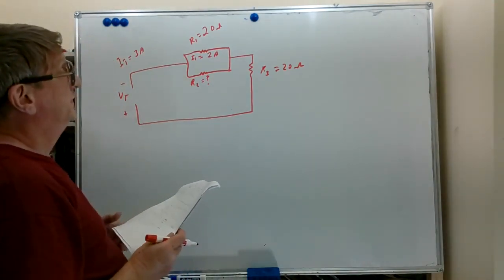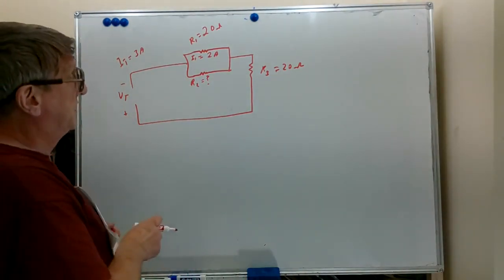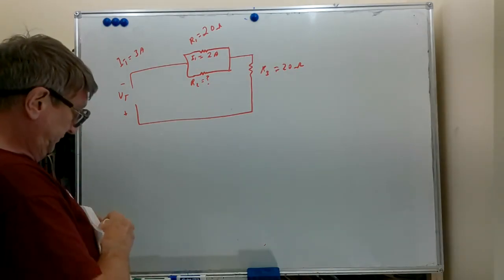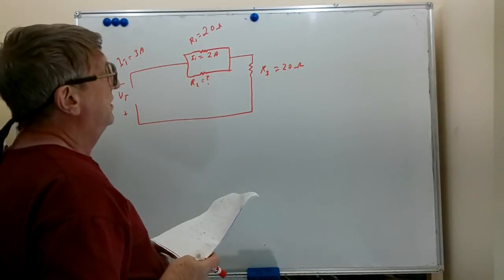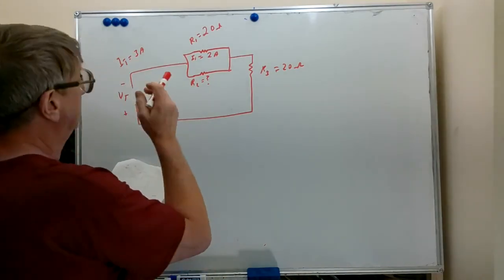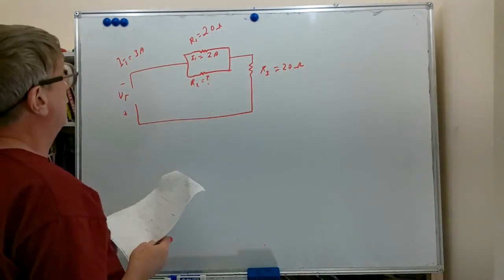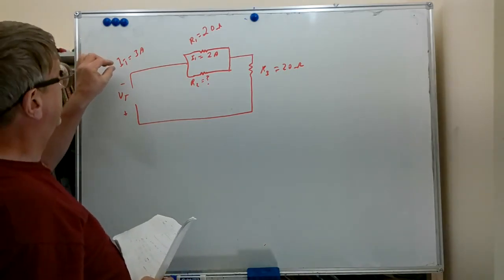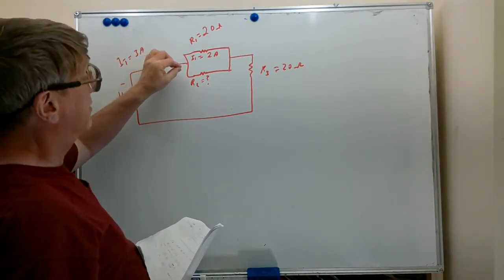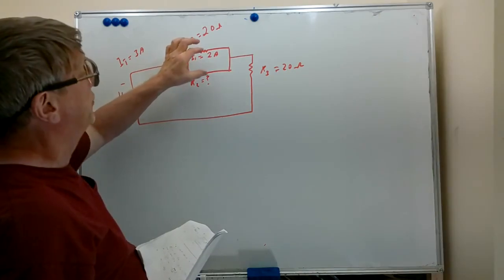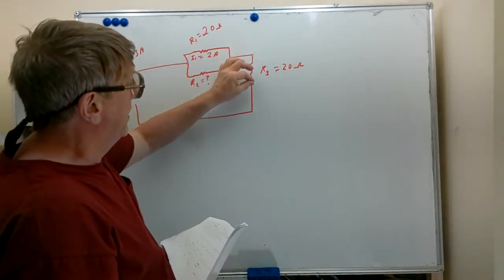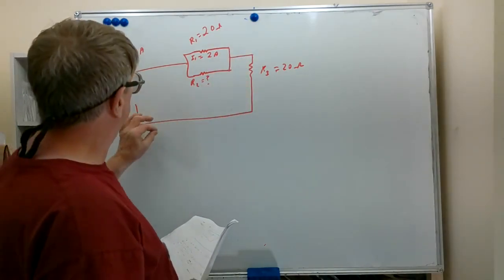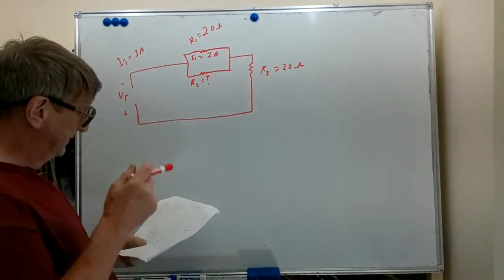So let's think about what we would like to find: all the voltages and all the currents in this circuit. So what do we know? We know that this IT travels in the main line here. It's going to split in some fashion through these two parallel branches. It's going to rejoin, and it's going to go right through R3 and around back to the source.